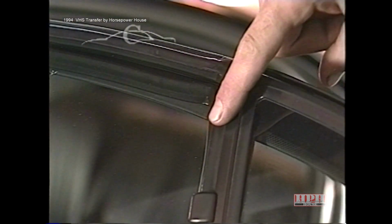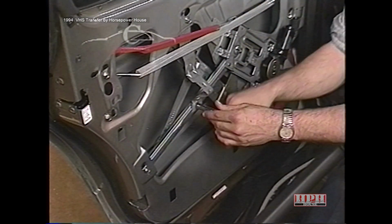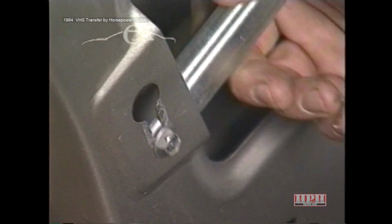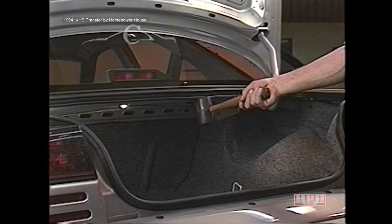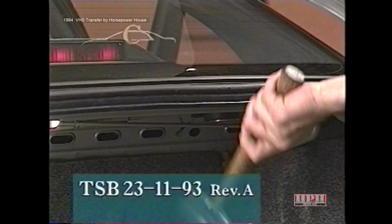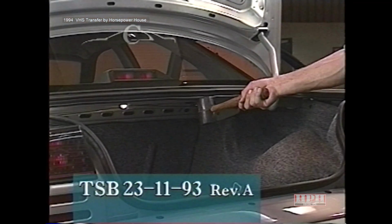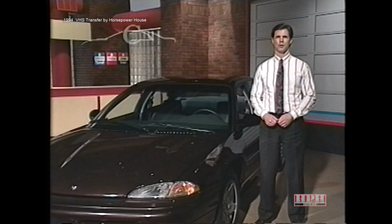If the window is to the outside of the weather strip, refer to your service manual and adjust the trailing arm of the window regulator to properly position the window. When a hissing or roar noise is present in the lower back seat area, refer to TSB number 231193 Revision A for the proper procedure and locations to adjust the rear deck lid opening weather strip using a rubber mallet.